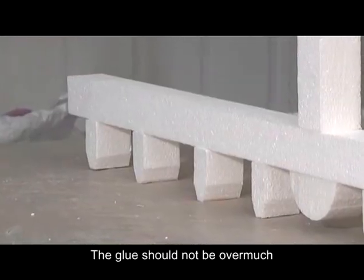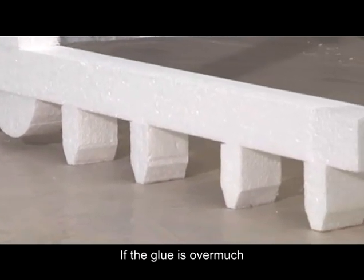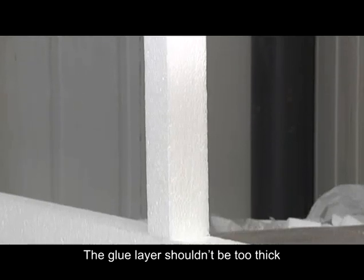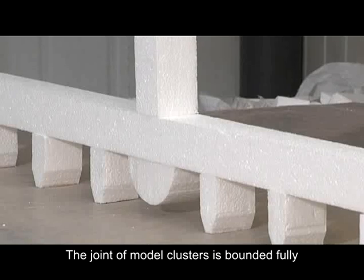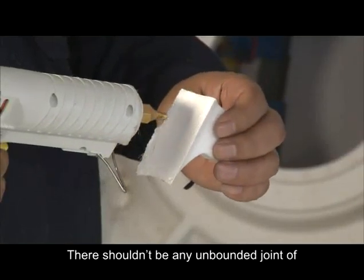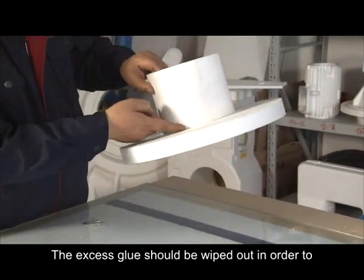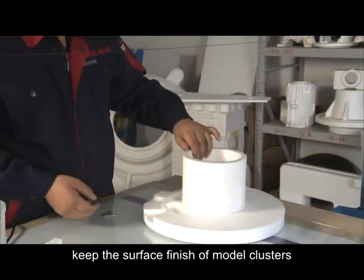The glue should not be overmuch when you glue the model clusters. If there is too much glue, more gas will be produced, which will cause hole defects. The glue layer shouldn't be too thick, lest the size is not precise. The joints of model clusters should be bonded fully. There shouldn't be any unbonded joint, lest the castings have defects. The excess glue shouldn't be wiped off, in order to keep the surface finish of the model clusters.